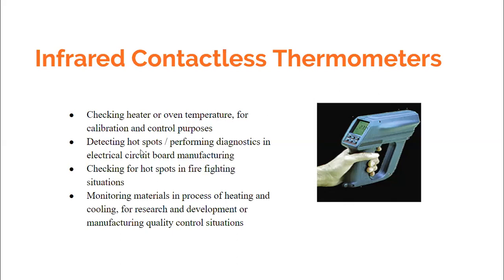Okay, this is very handy not only in the thermal audit, but it's also useful when you're diagnosing the electrical circuit for hot spots. Okay, if there is a short circuit and because of the short circuit, a particular wire gets hot, that also you can spot out by using this thermometer. So it's also useful in the safety audit, right? Or even in firefighting situations. And obviously, as I told you, it has wide applications in the thermal audit, and it's used widely because it is very convenient to use. Obviously, its initial cost is higher than the contact type of thermometers.